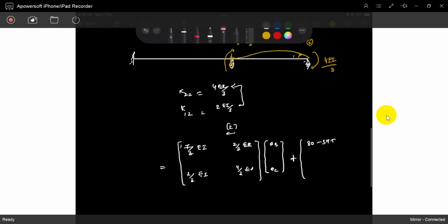So it is equal to 0, 0. You already said why it is 0, 0. Because theta B and theta C are released, finally it is 0. This is when we take everything as arrested or kinematically determined. Or later, if you allow those rotations, you will get finally 0, 0.